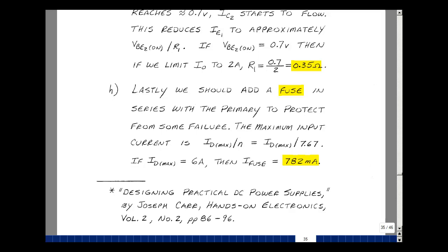I should make one last comment. A current limiter can respond much faster than a fuse. Typically, a current limiter is going to respond in hundreds of microseconds, whereas a fuse is in hundreds of milliseconds. And this is supplemental problem 319.